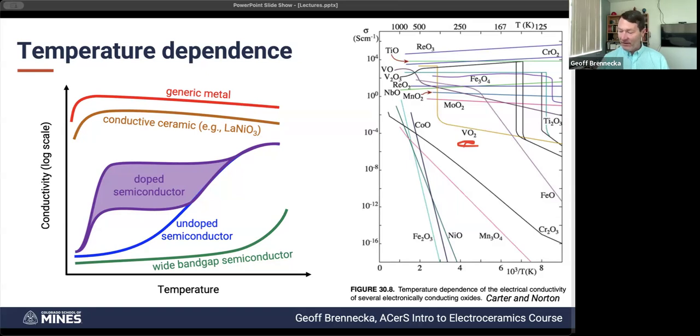The challenge with that one is that the native temperature for that phase transition is about 150 C, I believe, 170 C, something like that. It's too hot to be useful for residential windows, but people are doping this vanadium with niobium or other materials to shift that phase transition to lower temperature. So you can have a completely passive window that regulates the temperature in your house just by adjusting how much sunlight is coming in based on the temperature itself.